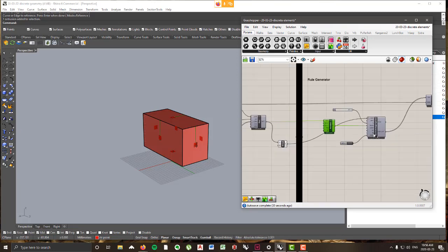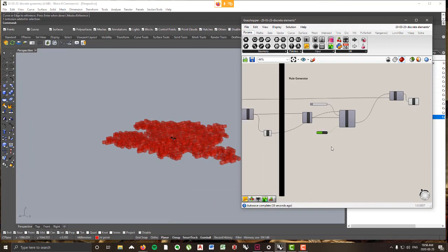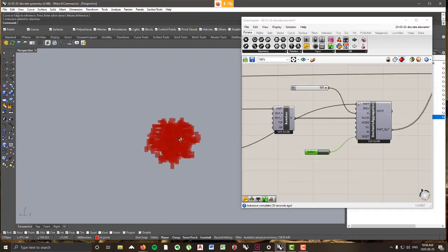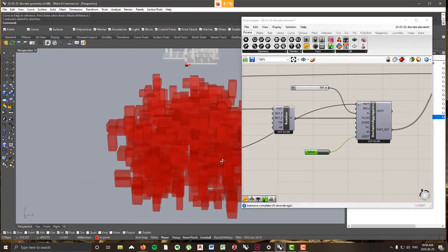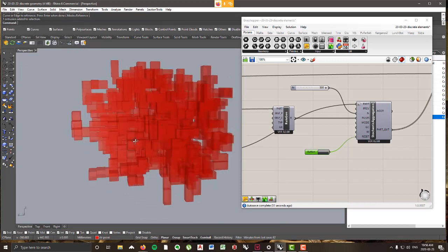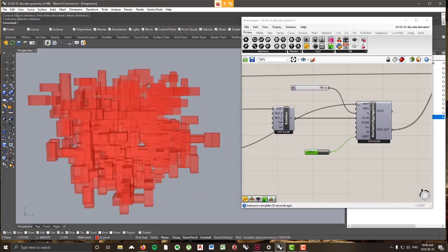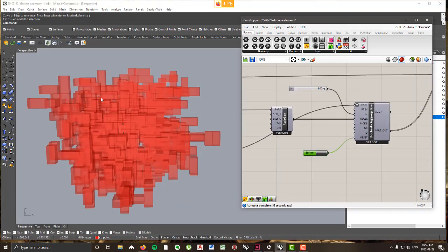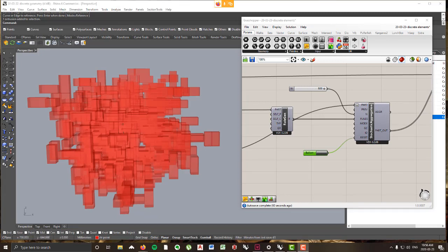So by default, if we preview on our geometry, hit reset, what you're going to see happens is now we're starting to array in 3 directions, right? We're starting to array both in 2D and also in 3D. And what's happening is that our rectangle is starting to tilt 90 degrees in the vertical direction. So it's starting to rotate here, like this way instead of just in that XY plane.